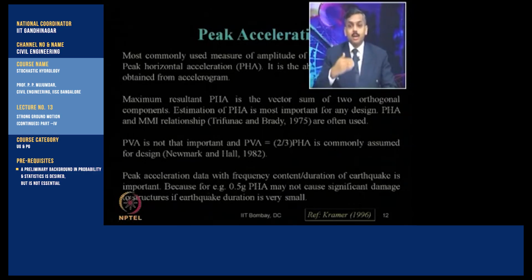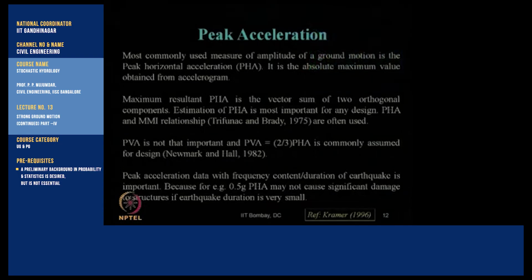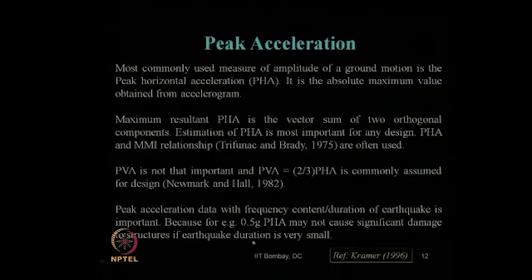It needs certain time to respond. So, if at a site a PHA value of 0.35 g, which is much lower than this, continues for a duration of say 20 seconds, that will be more damaging to the structures than this 0.5 g PHA.